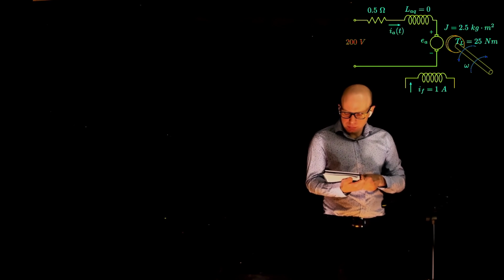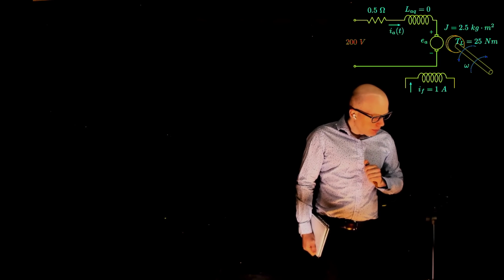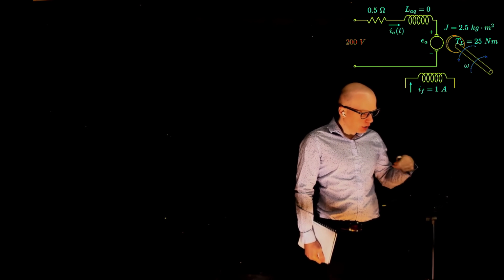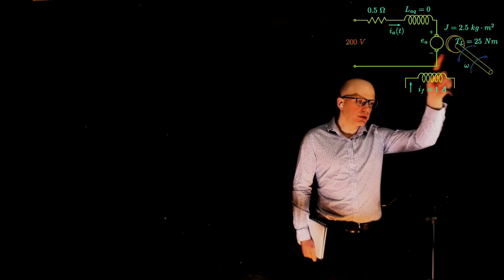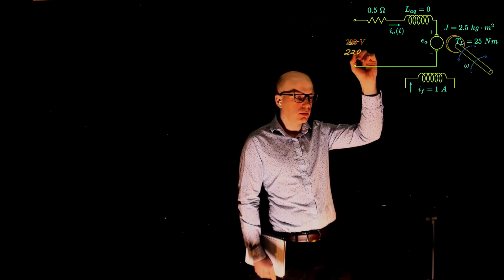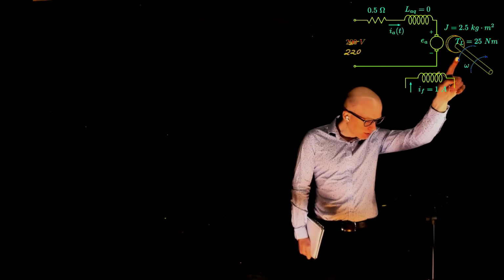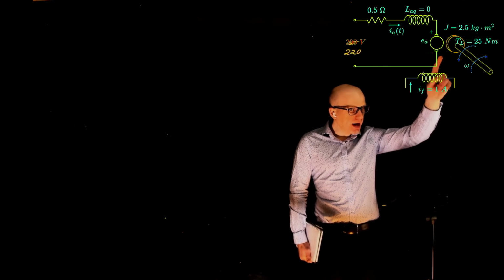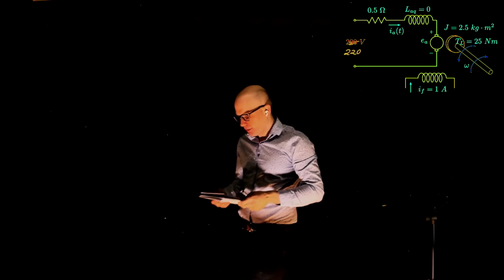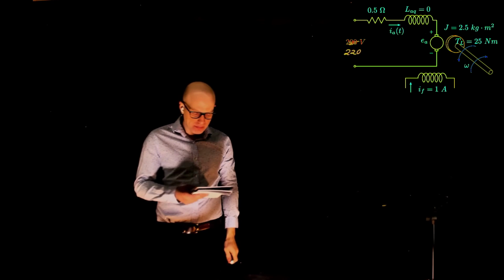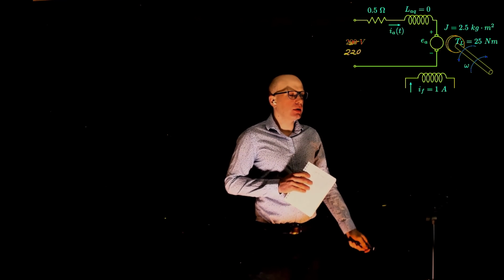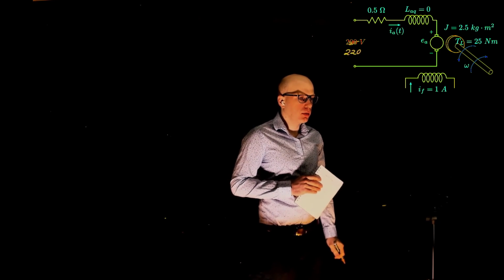All right, so let's start with this one. The important information that you have here is that the motor operates as an open circuit, so nothing connected here, and again this is 220. If you rotate at 2000 RPM with 1 amp here, we get an armature voltage of 220 volts. Why is that information important? What can we get from it? It means the torque is 0. We know the torque is 0, yes, but what else can we deduce from that information?